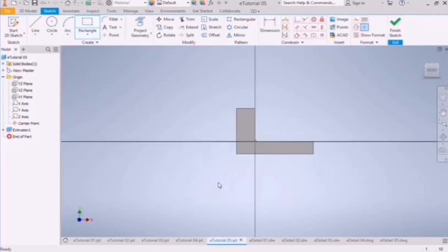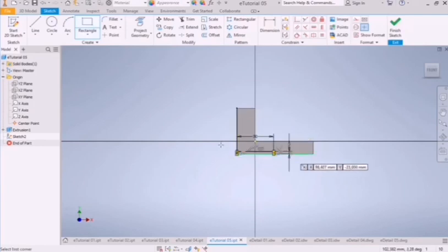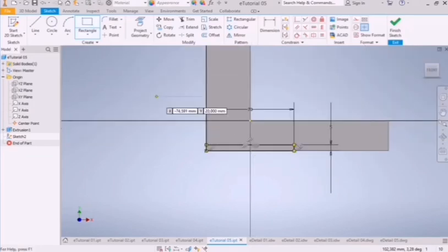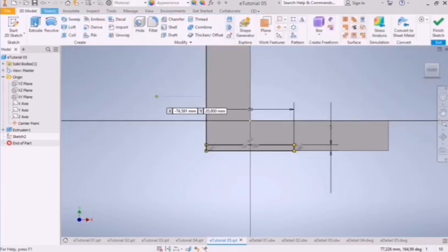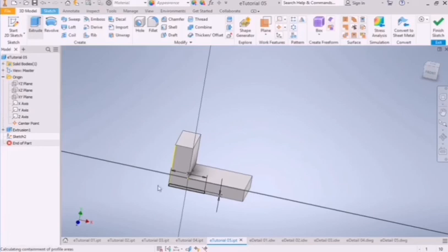We sketch from our front view as per our arrow has shown us. And then from here the project geometry is already projected. It's 70 and then 5. Then we enter. Yeah, it's dimensioned as what the question paper has specified.